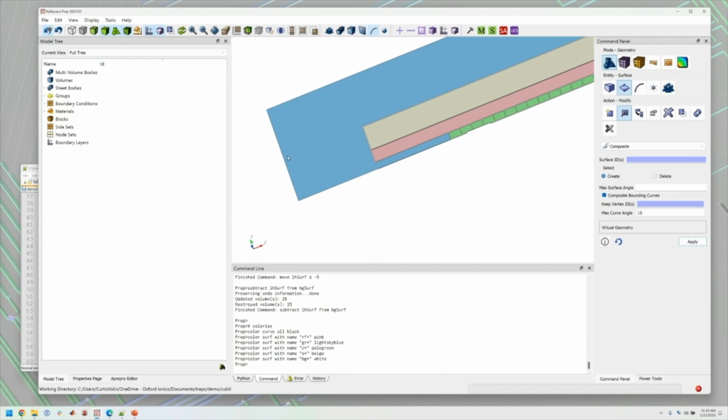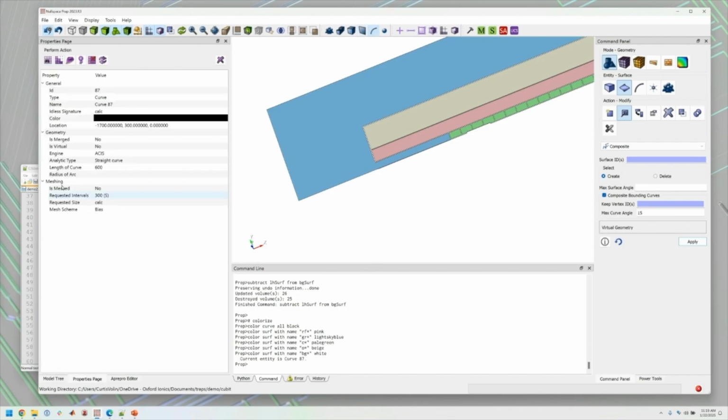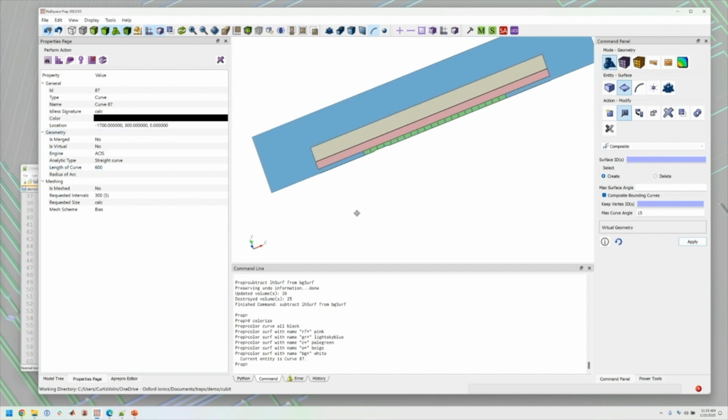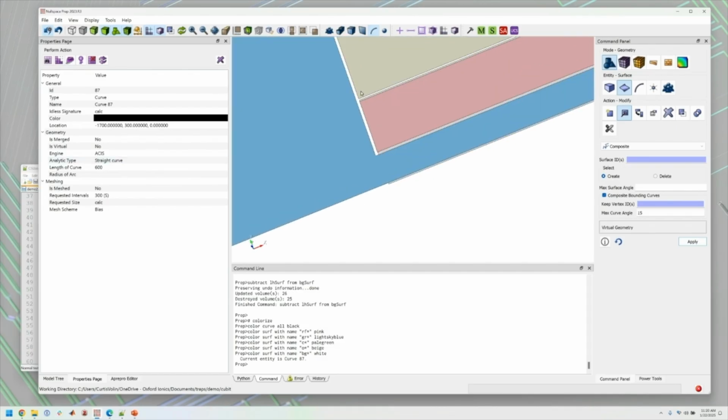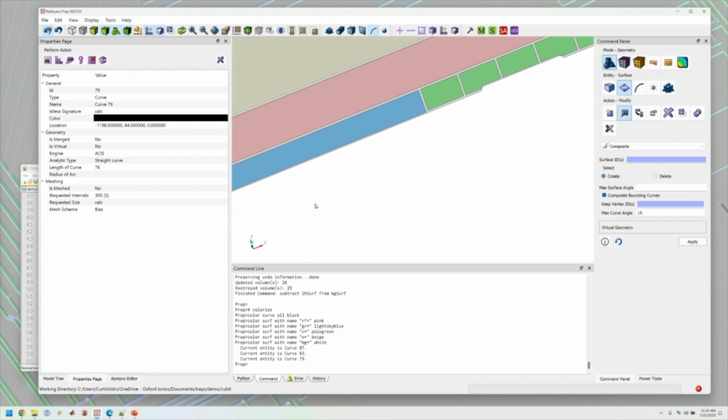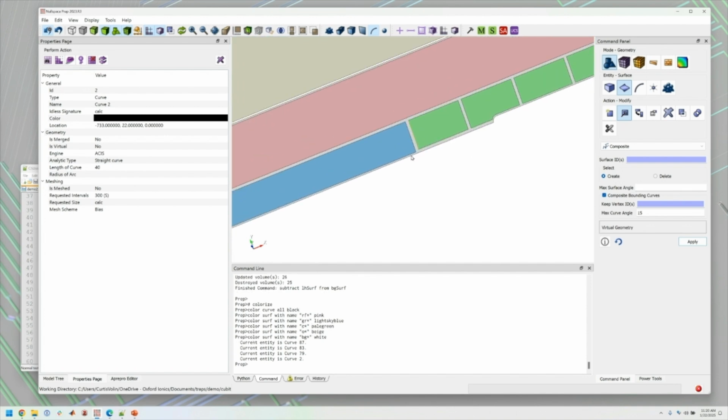but just looking at some of the dimensions of the trap, if I look at the properties here, this curve's length is 600 microns, so this would be a 1.2 millimeter isthmus. The entire trap model is 3.4 millimeters long. I just truncated this at some arbitrary point without putting a whole lot of thought into it. Obviously, we can simulate things that are much larger. The outer electrode is 150 microns wide. Our electrode is 76. I just kind of rounded off some numbers for my own convenience.